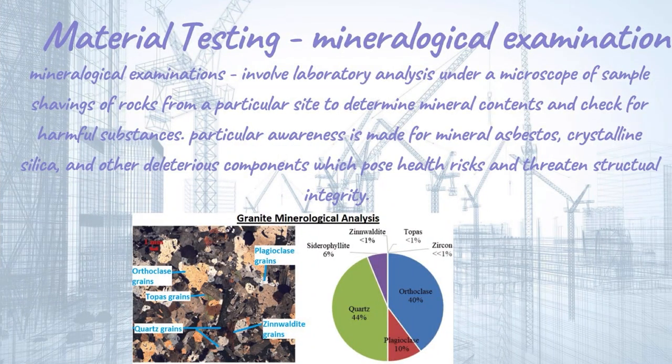Mineralogical examinations. So this is mostly used for rock samples. So it's to determine the mineral content within the rocks. So it can be used to detect harmful substances within the material, such as asbestos, and it can also determine what the strength will be like within the material. Such as in granite, which is used in many building applications, you want to make sure that it has sufficient quartz, so that it has sufficient strength, and you want as minimal impurities as you can, so that it doesn't have big failure points, so it's not going to crack. So you basically just chop it open, look at it in a microscope.